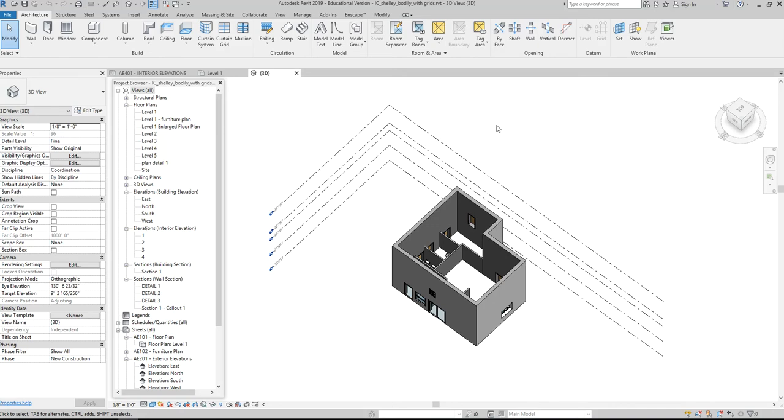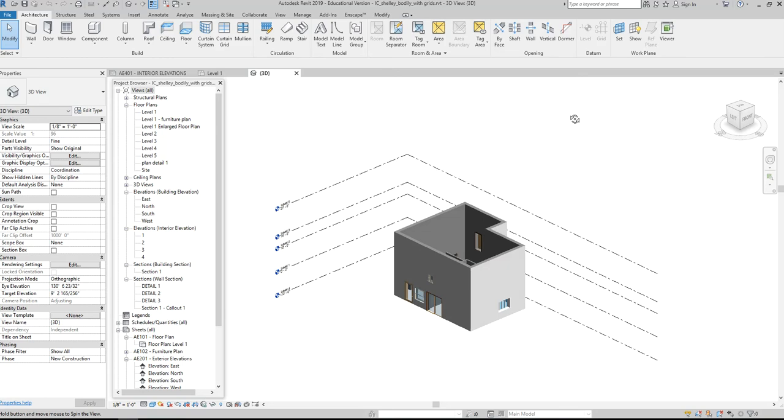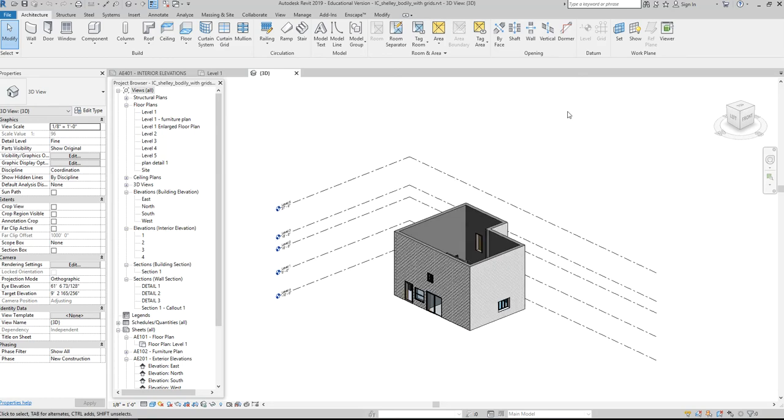When we create a floor, one thing I want to remind you is that just like a wall, we assign them to a level. And really just like anything in Revit, we assign them to a level, right? So if our floor is in the lower level, we assign it to the lower level. When we create one on the main level, we assign it to the main level, all right? Something we're not going to get hugely into today, but I just want to tell you that you have the option to do it in Revit, is that you have the ability to create a sloped, but also a completely flat floor, all right? And in a minute, I'm going to talk about means and methods of how you can create floors. So that'll make sense when I get to it.